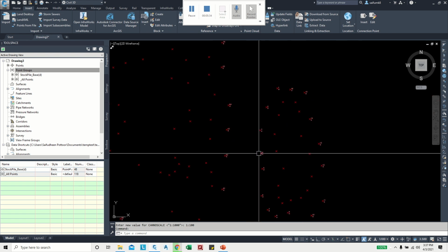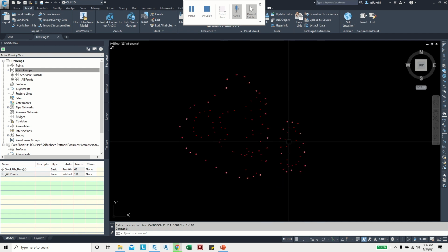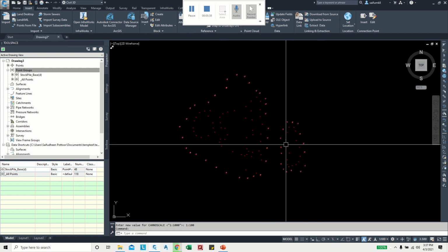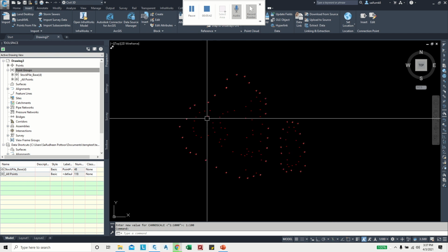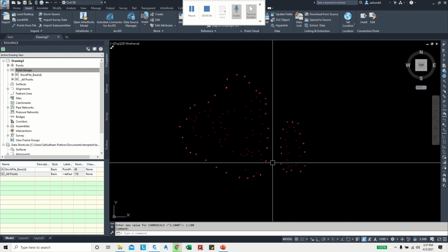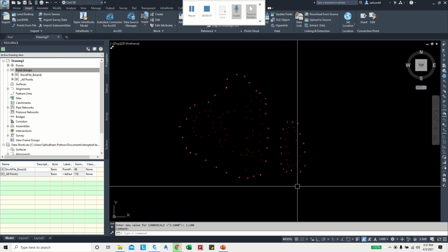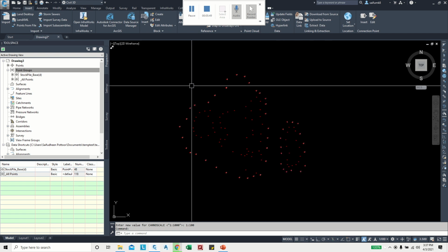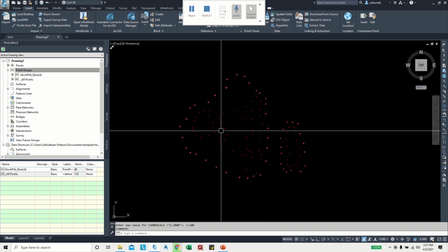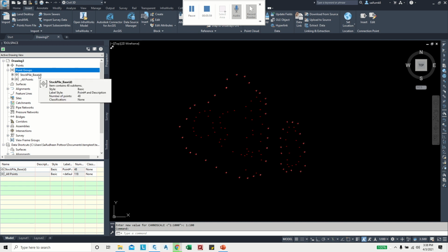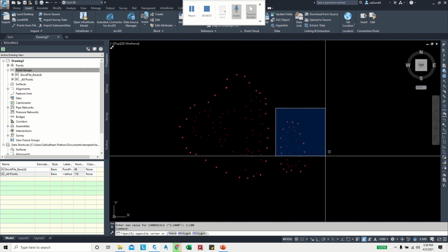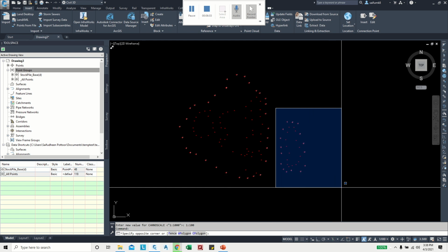Okay, so we can also see here different ones. So in this situation we have two stockpiles in this survey point file, so we can make it separate for stockpile 1 and 2. So the bigger one we can make it stockpile 1, and from this group which we created recently, stockpile base D, we can exclude all the other stockpile points.